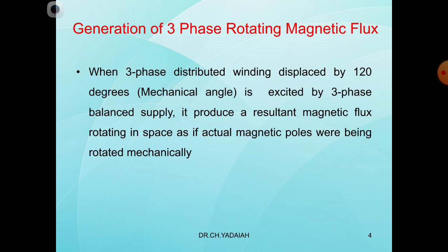At the same time, based on Faraday's laws of electromagnetic induction, since the relative motion between the stator magnetic field and rotor damper windings is zero, d phi by dt is equal to 0. Then there is no induced EMF in the damper windings. No flux is developed. Then they are simply conductors, only copper wires.